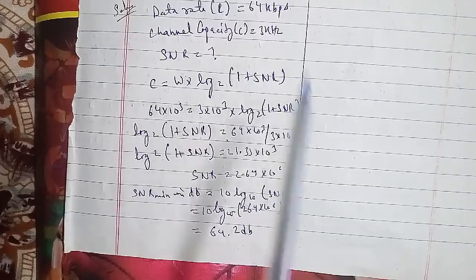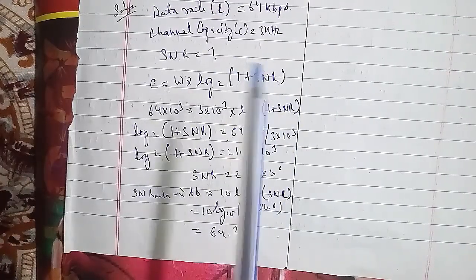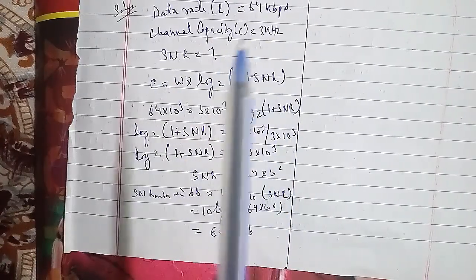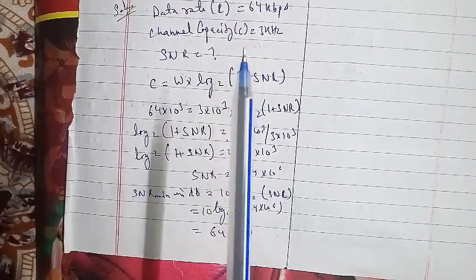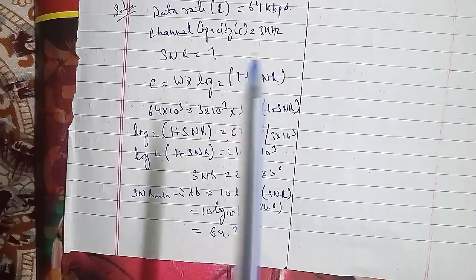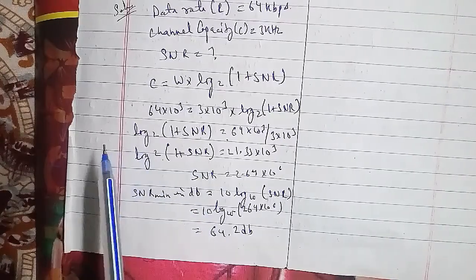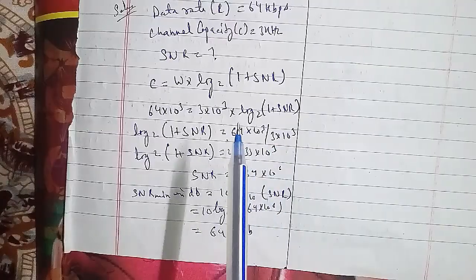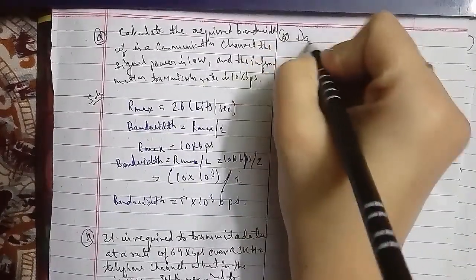Here, the Nyquist theorem gives the different bit rate formulas that define the theoretical maximum bit rate, and it says that if you have a function whose Fourier spectrum does not contain any sines or cosines above f, then by sampling the function at a frequency of 2f, you capture all the information there is. Thus the Nyquist theorem is true for all media. The Nyquist theorem gives the upper bound for the bit rate of the transmission system by calculating the bit rate directly from the number of bits in the symbols or the signal levels and the bandwidth of the system as well.